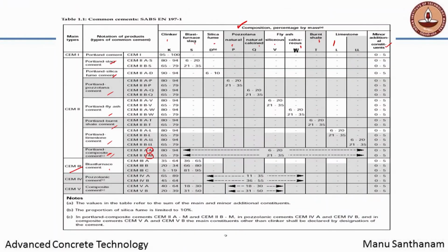And you will see later when you talk about high performance concrete that the best way to get very high durability and strength in concrete at fairly controlled cement contents is to ensure that you have ternary blended systems inside. So, here there is a possibility of even producing a cement of that type. Okay. Type 3 or CEM 3 is blast furnace cement, which has 3 A, B and C depending upon the extent of replacement of cement by slag.